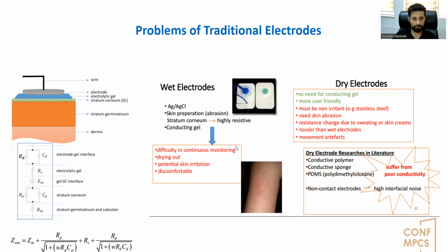While measuring electrophysiological signals from the body surface, the contact impedance between the electrodes and the skin surface also has a significant effect. The surface of the skin is abraded to reduce the impedance by cleaning the skin surface from dead cells, fats, and some hairs. These processes may cause pain and irritation of the skin surface.